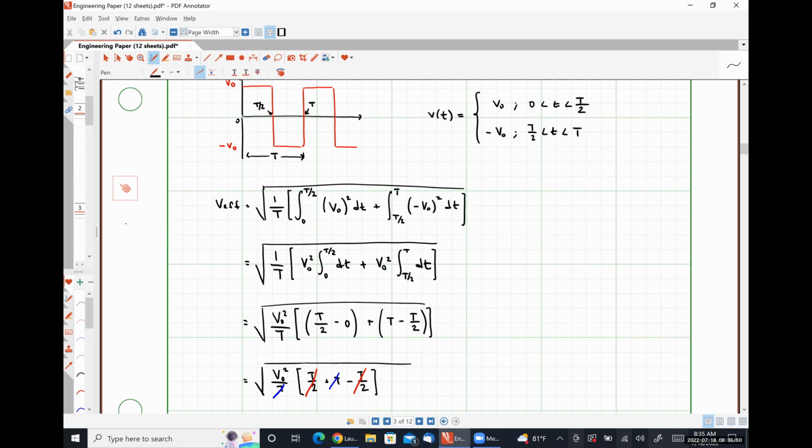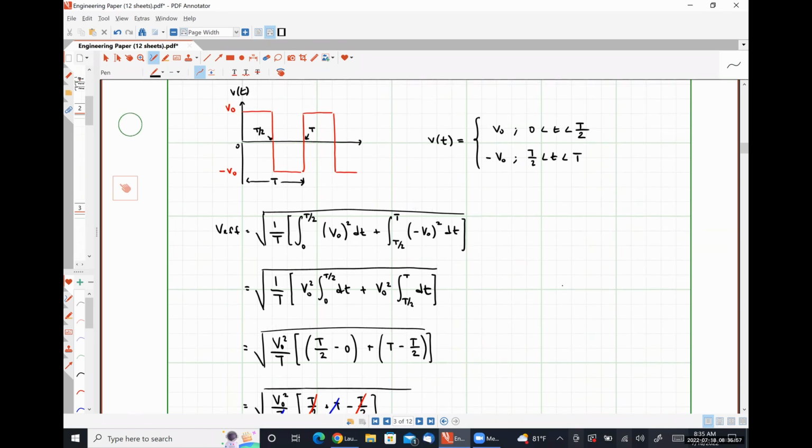Now, if we had a series of rectangular pulses instead of a square wave, so I'm just going to draw this on top, but we're not going to do the analysis because I asked you to do it in your homework. But if we had a signal like this, that I'm doing here in blue, where we effectively didn't have the matching negative rectangular pulse, we'll find out that our effective value will be appreciably different, okay?